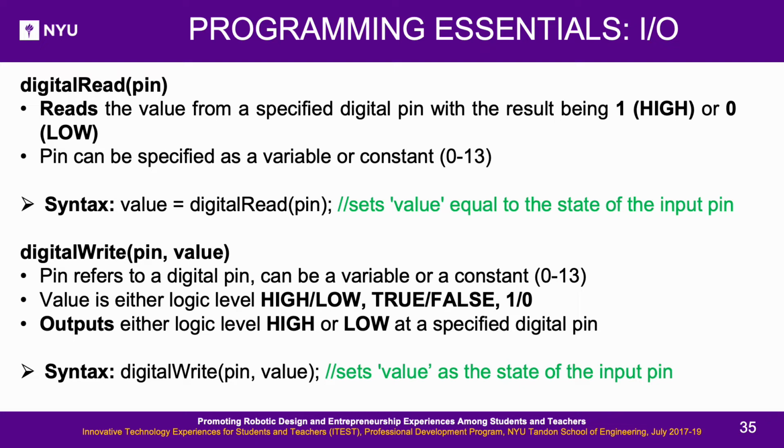digitalRead(pin). It reads the value from the specified digital pin number, and the result is 1, meaning high, or 0, meaning low. Pin can be specified as a variable or constant from 0 to 13. Syntax: value = digitalRead(pin). This sets value equal to the state of the input pin.